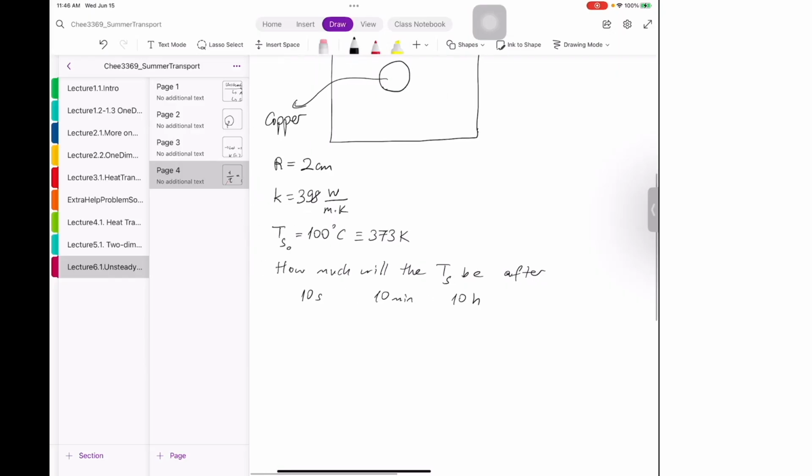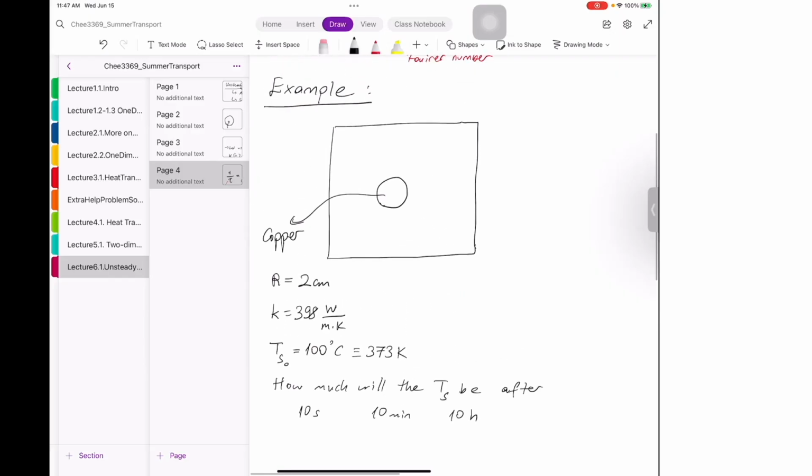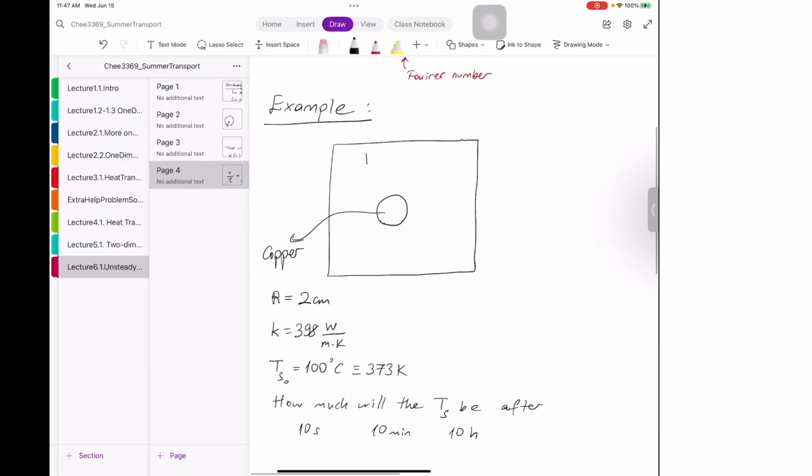And let me give the h. Okay, h. It's in an environment, so let's think about this like a well circulating air at Tf equal to 273 Kelvin. And h you can take approximately as 10 watts per meter square Kelvin.